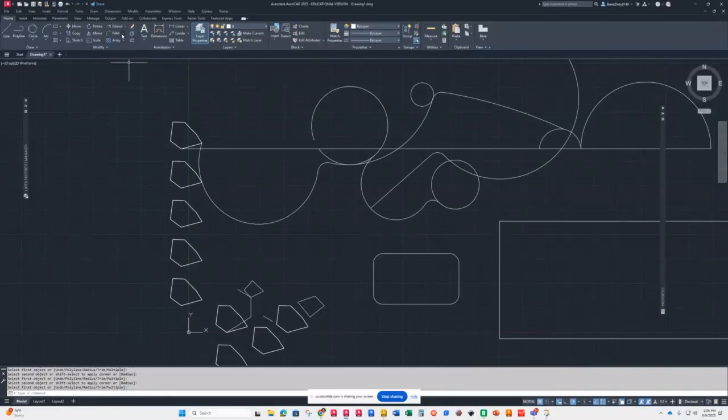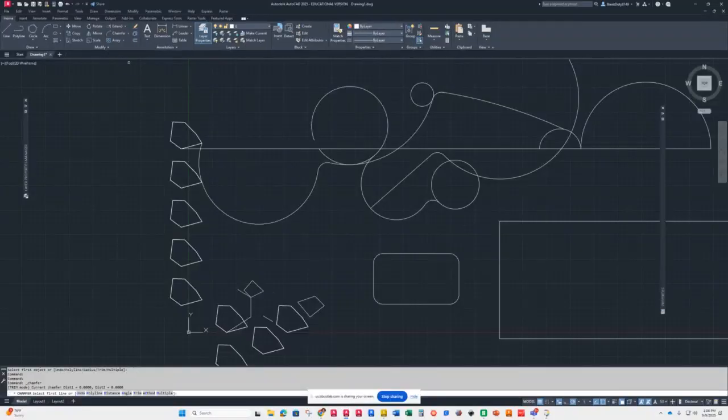All right, so the next thing you have are chamfers. On a chamfer, you put in a distance, or a distance and an angle. Most of your chamfers are going to be at 45 degrees. In this class, they're going to be at 45 degrees. Maybe in another class, you might have a 30-degree one. Well, when you measure an angle, you've got two options.